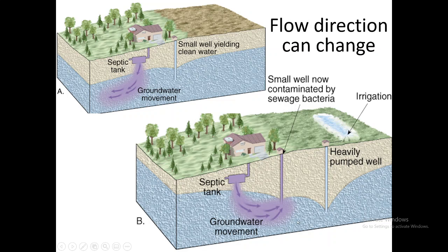When the water table level is reducing in this area due to the cone of depression, then all the contamination existing at this point will be shifted to the reverse direction, and it will be under the influence of this cone of depression. And now, due to this shifting of water table level, this installed monitoring well will be having all the contamination in it.